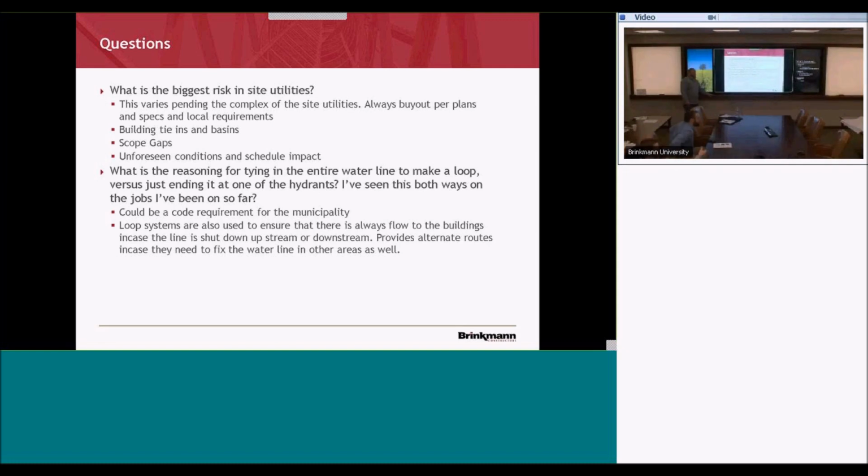Even when you know where the utilities are, you're always recommended to go slow around them. Because you never know. I mean, just a jerk of the bucket or something could poke a hole in an 8-inch gas line along 64. Just saying. And theoretically, stuff like that could happen. There's a lot of horror stories around about finding utilities the wrong way.